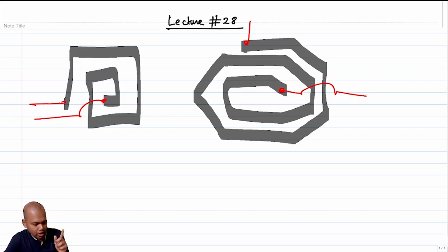Another problem of these structures is that when you draw a loop, what is the genesis of the inductance? It is basically the flux that is cutting the area of the loop, right? So the larger the area, the more the inductance. Now the whole purpose of having these concentric loops is to say that I will have multiple of these loops, and the fluxes will couple, and I am going to get larger inductances, right? But the problem is that the center loop, as you can see, obviously has a very small area with respect to the outer loop, correct?